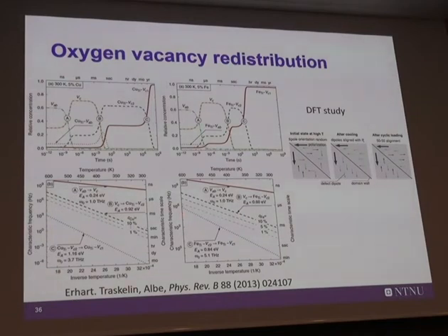If you go to low temperatures, you see that in some cases, especially for copper, the time scale of this relaxation is fairly long, so it takes some time before the oxygen vacancies are trapped by the acceptor dopant. But you don't need to go high up in temperature. The calculation also shows that it does not really depend on the concentration of the acceptor dopant.